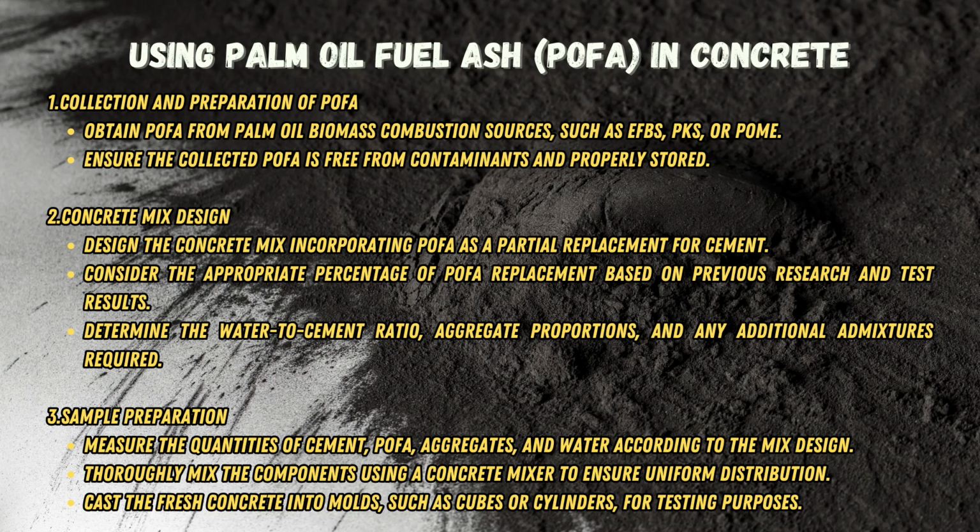Next, concrete mix design. Design the concrete mix incorporating POFA as a partial replacement for cement. Consider the appropriate percentage of POFA replacement based on previous research and test results. Determine the water to cement ratio, aggregate proportions, and any additional admixtures required.